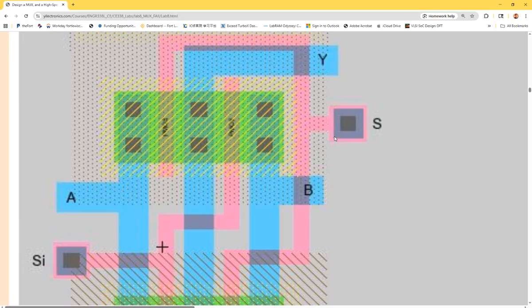So whenever you are trying to connect the ports to the gate, because the gate requires some signal to turn it on, like voltage source, right? So you eventually need the metal to connect to it. So in that case, when you have all the gates or the poly here, and you do need a metal one with it. So this is actually a component from the library. I grab it, resize it, and connect poly from here to here, because this one has both poly and metal one and the via.